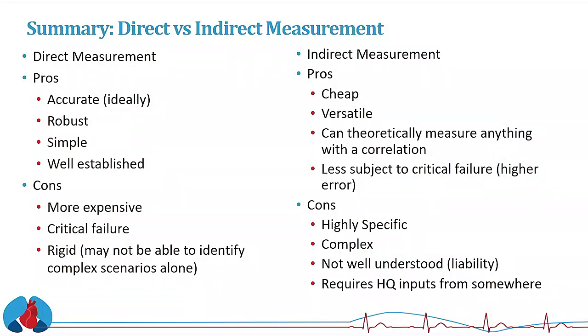So when we then did that HVAD flow estimator study, and we used the repaired devices with the copper cables, the estimator was constantly reading above 10 litres per minute, which is the maximum that it can read. The reason for that was we changed the resistance of the cable, which changed the calculation, which then changed the output.